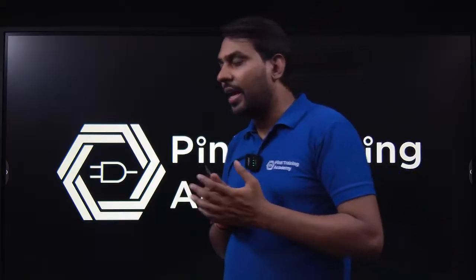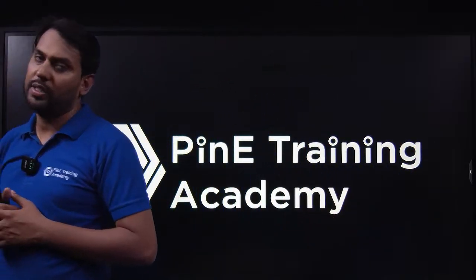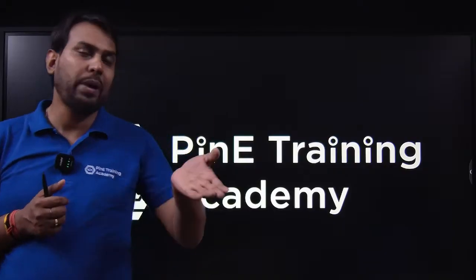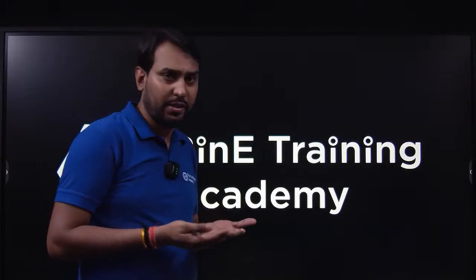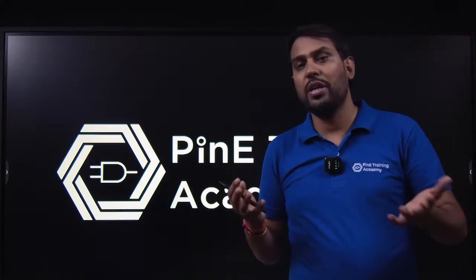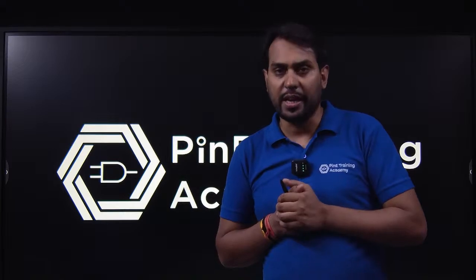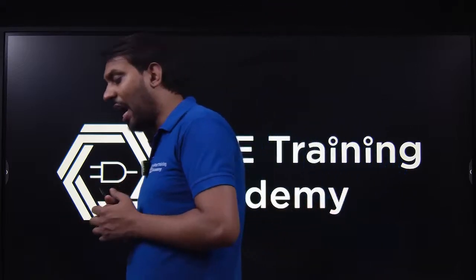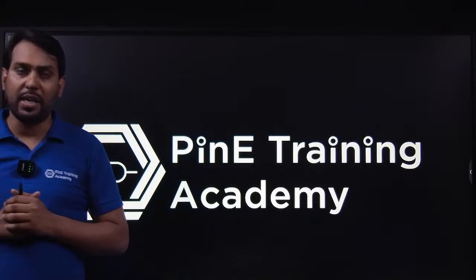Then we talk about what the effect will be if you have a diode. If you have a diode in parallel with a resistance, the diode is a unidirectional device. It will follow that one path. If you have an anode and a cathode, and the anode potential is greater than the cathode potential, it will behave like a short circuit, or if you have a cut-in voltage, it will be V gamma, and it will charge the capacitor suddenly.